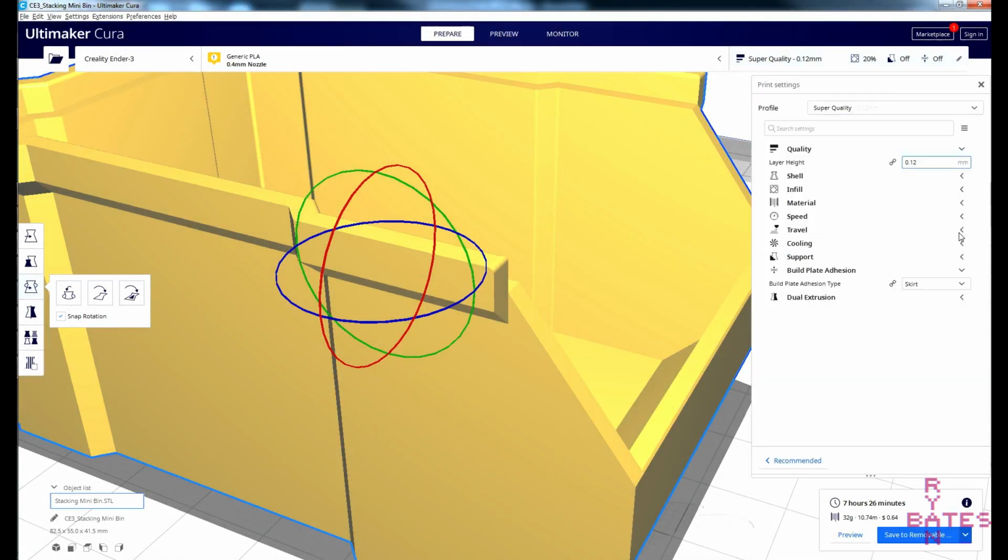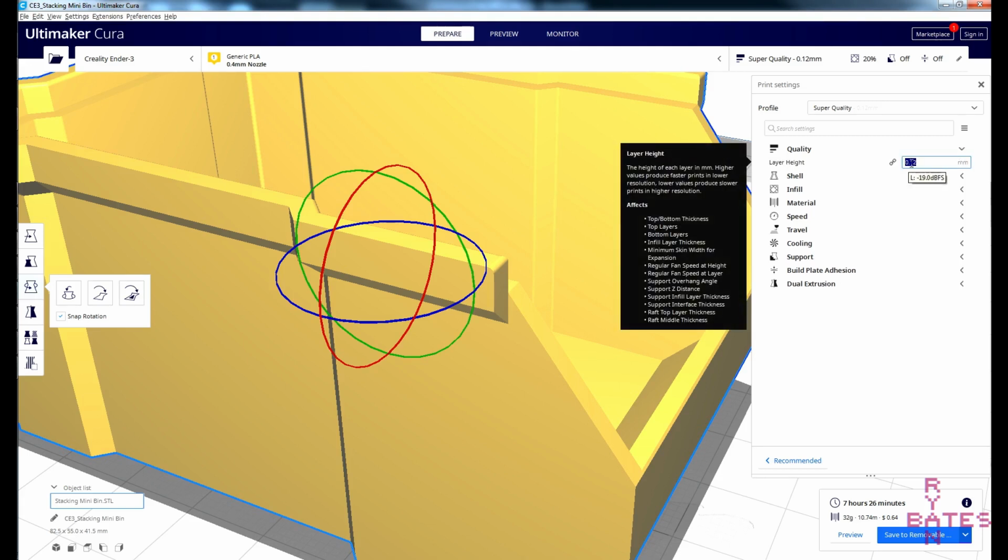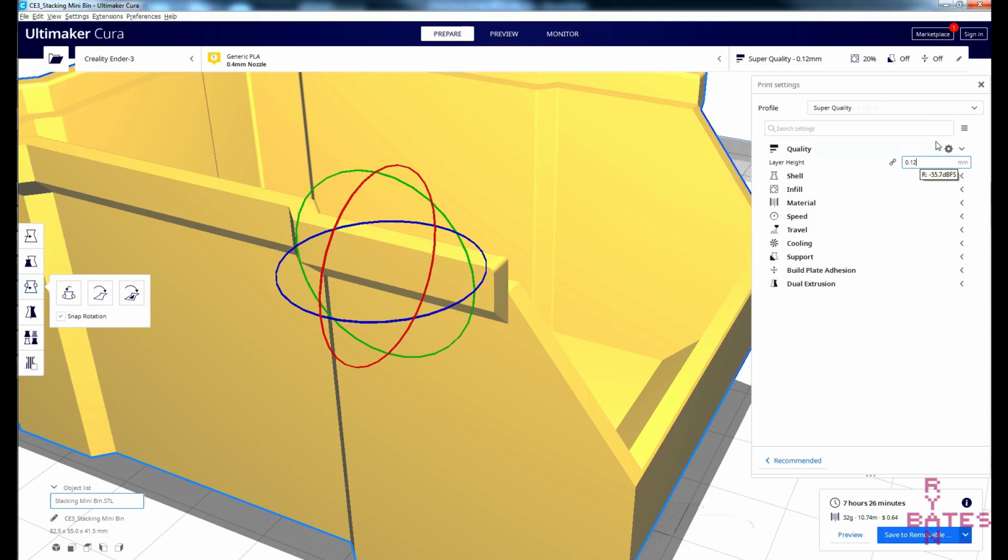This is a general term that covers two main characteristics, layer height and print speed. Both are directly related to each other. This can be best seen by the estimated print time when slicing your part. Low quality settings are always faster compared to high quality settings. The difference here is how many layers your model is sliced into. High quality or high detail slices your parts into more layers, each layer being thinner compared to a low quality slice.